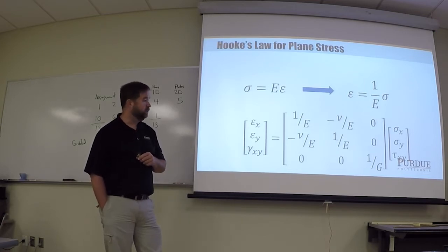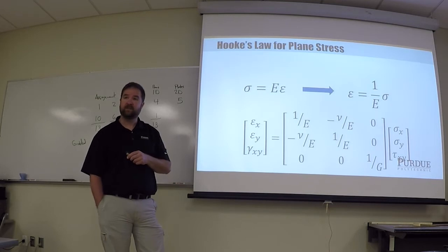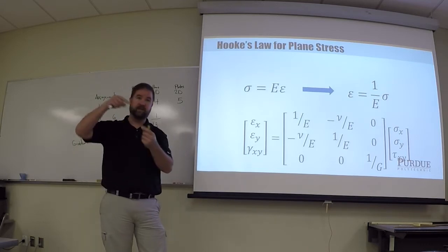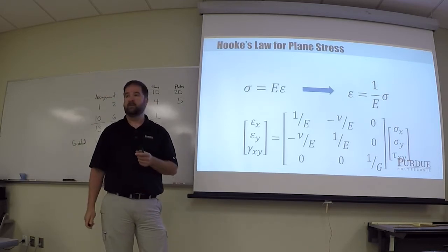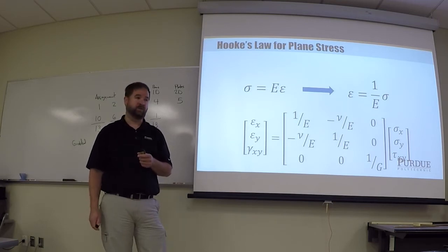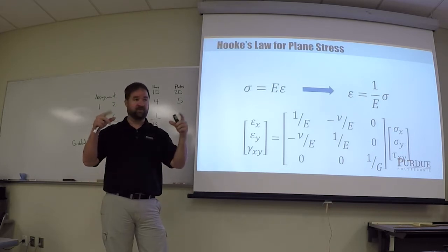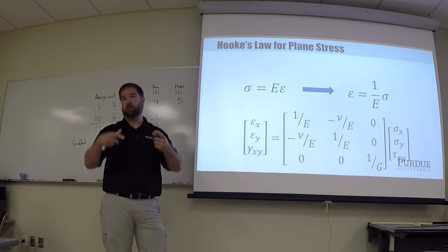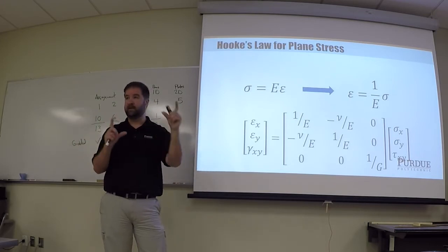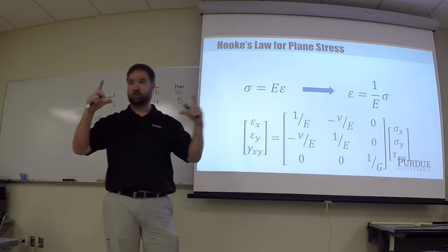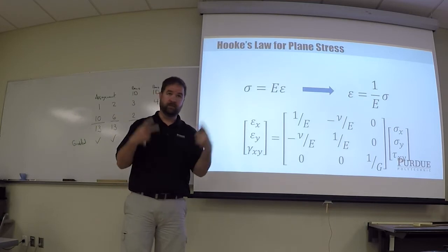Okay? We get to 2 dimensions, a biaxial state of stress. So think about scenarios where we have forces that are pulling down the length of something as well as pulling crosswise on it. We have stress in multiple directions. A really simple example of that is think about a balloon. If you inflate a balloon, it has stress that is going in 2 directions. Or, typically simplified down to 2 directions. But essentially you have an infinite number of directions as the balloon stretches because of the pressure inside of the balloon.